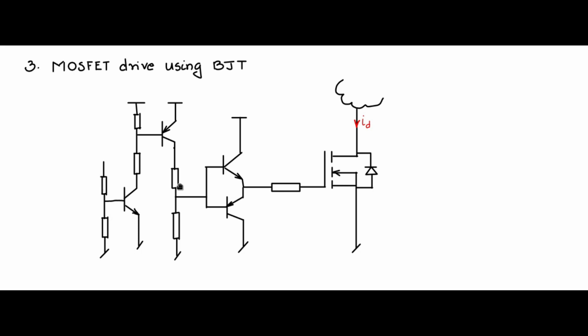So you see, like this, stage by stage the current starts decreasing. The current here, the Ig plus whatever requirement here will be lesser here on the base side of this. On the base side of the PNP it will be still further lesser, till at the source VB it can be of the order of microamps to milliamps. So let us say we need to give a pulse in this fashion here. Let us say this is Q1, R1, Q2, Q3, Q4.